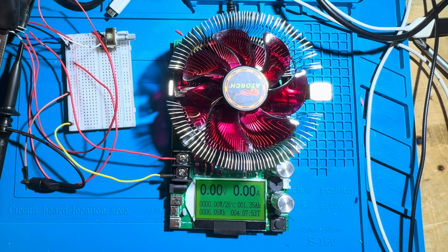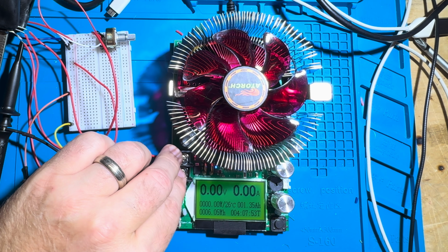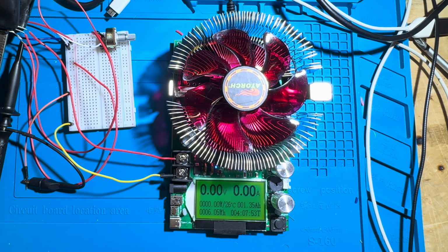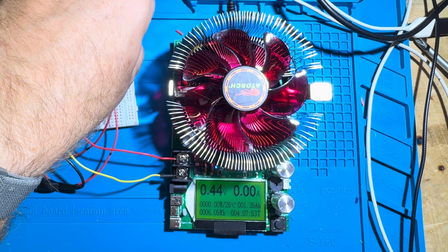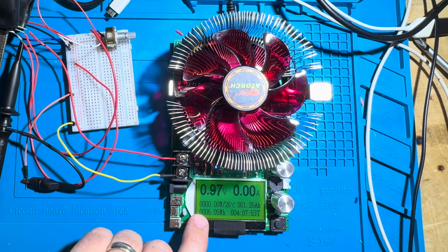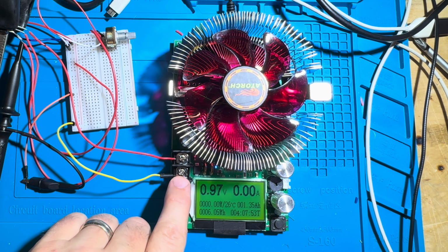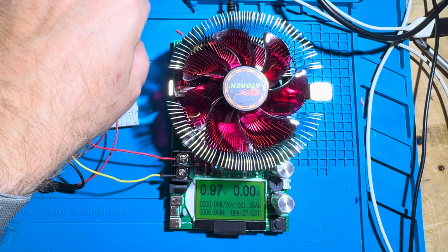So there's a voltage drop across the MOSFET, and the load sees the remainder of 12 volts minus the voltage drop across the MOSFET. So now I've got about 4 volts going into the gate, which is producing about a volt of voltage drop across the load, which means there are 11 volts of voltage drop across the MOSFET.